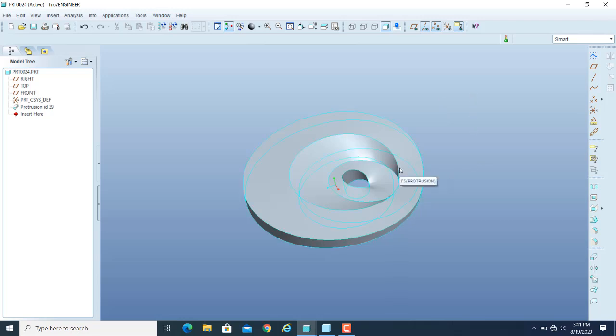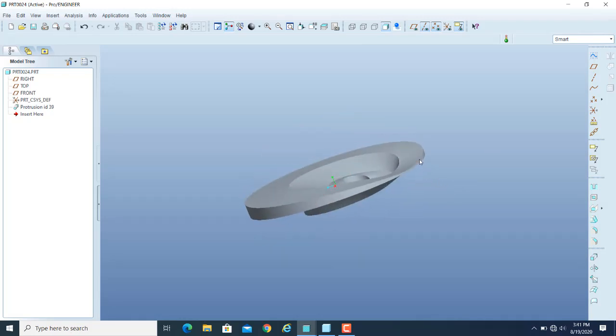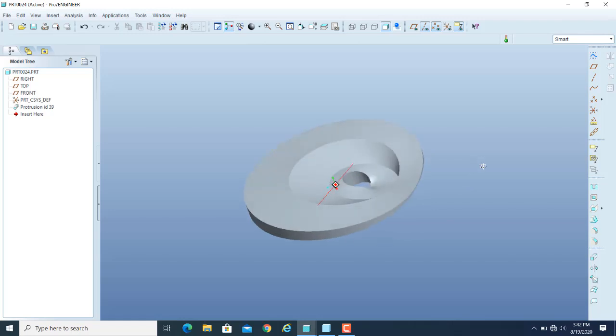So in parallel blending, parallel is alternative of extrude. Extrude में आपके पास जो है वो 90 degree पे generation होती है. So similarly you can get that 90 degree generation or normal generation using the parallel blending, but in addition to that you can also change the cross-sectional area of that particular solid. And similarly here in revolve or rotational blend, we can revolve an entity to convert it to a solid, and in addition to that we can also change the cross-sectional areas during that revolution.